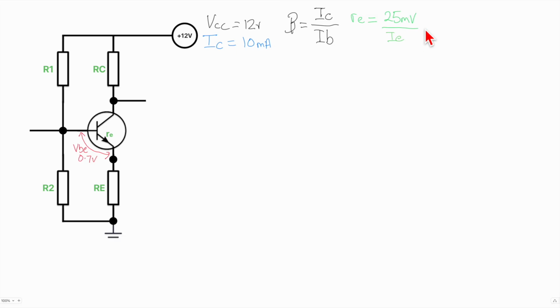Now, actually, this is not a very high amount, because if we do the sums here, we know that we're going to shoot for 10 milliamps current going through our collector, and actually we can say that the current at the emitter will be approximately 10 milliamps as well.